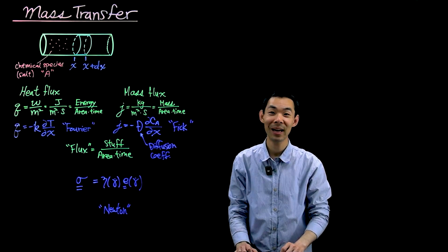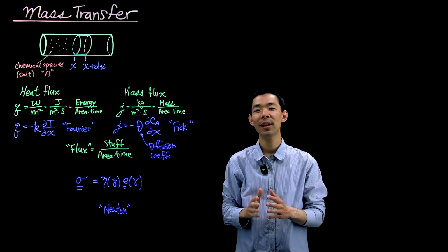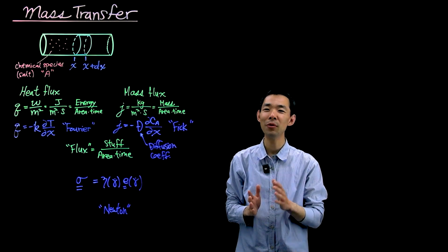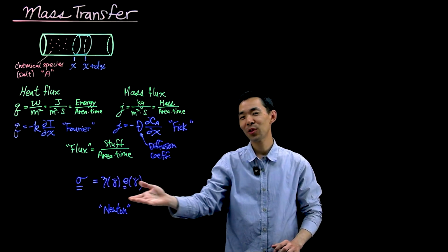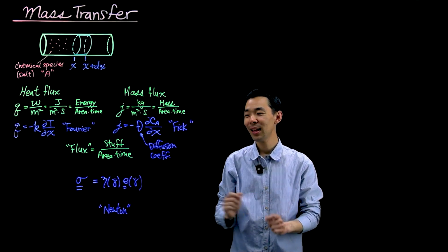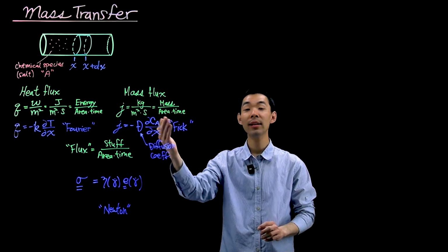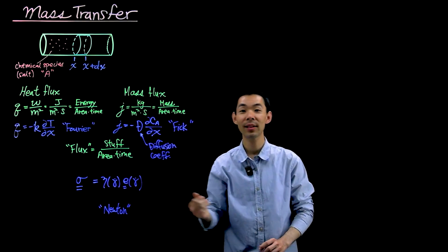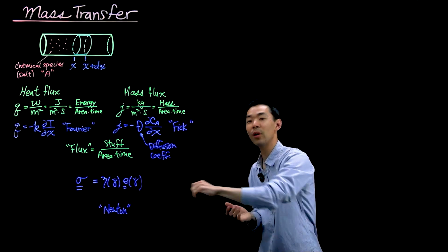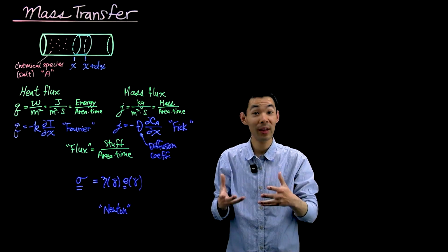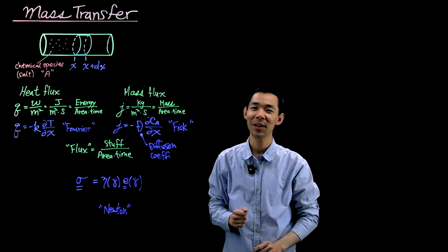So in the field of fluid mechanics, the simplest relationship between the flux and your conserved species is called a Newtonian relationship or Newtonian constitutive relation. I wrote it in the most general form, so it's a little bit harder to see. But on the right-hand side, you'll have a gradient of the velocity, similar to the gradient of the concentration. The proportionality constant is called the viscosity. How hard is it to shear and make a fluid flow across a material or within a material? And that is equal to the left-hand side, which is called the stress tensor.